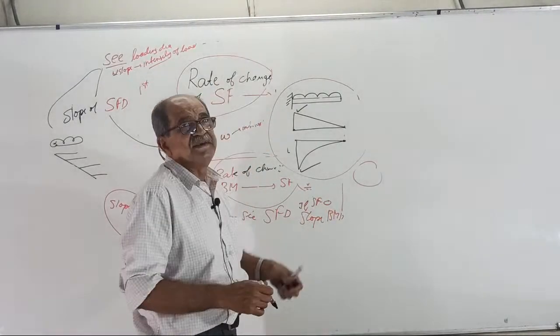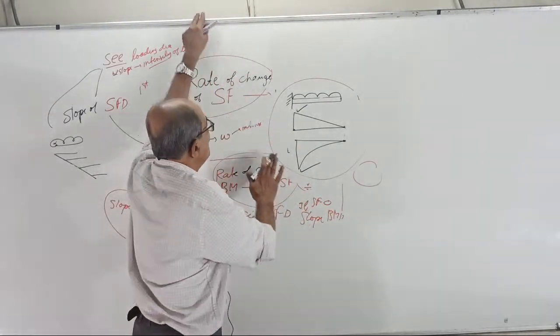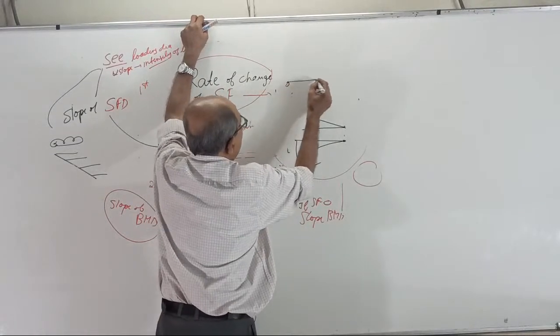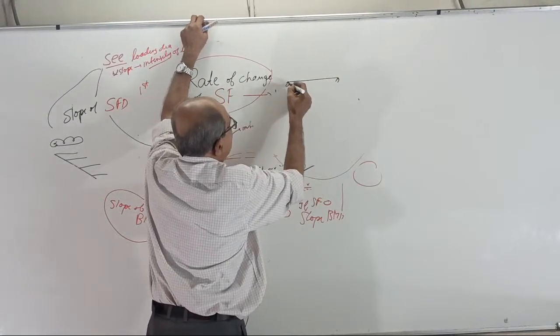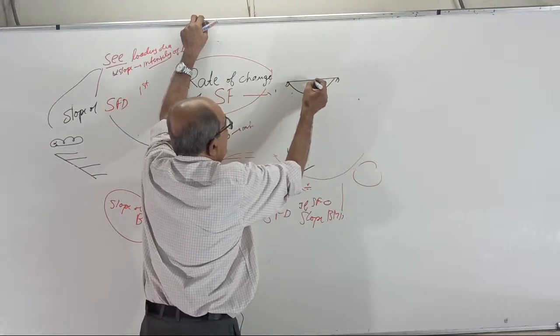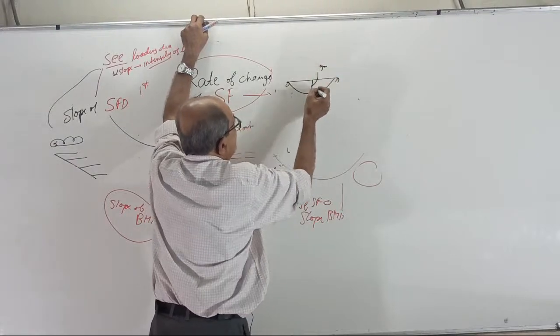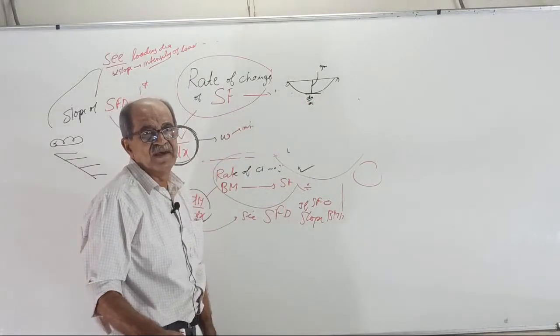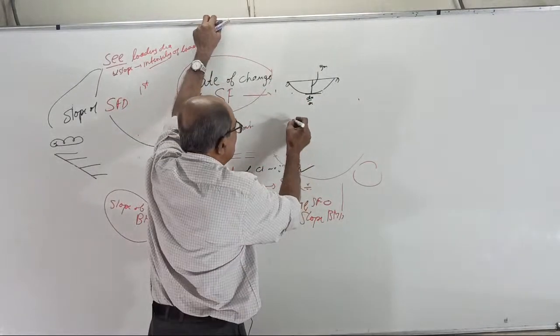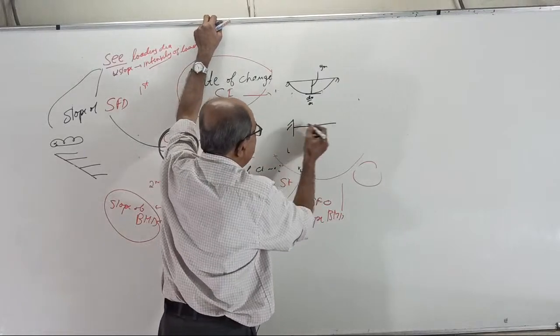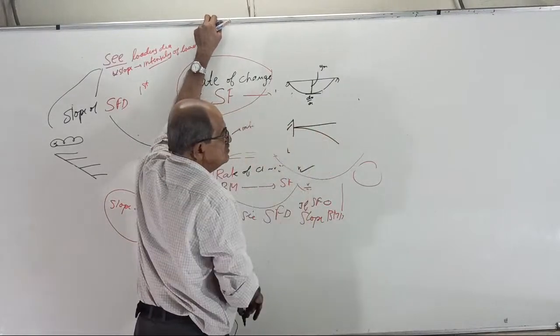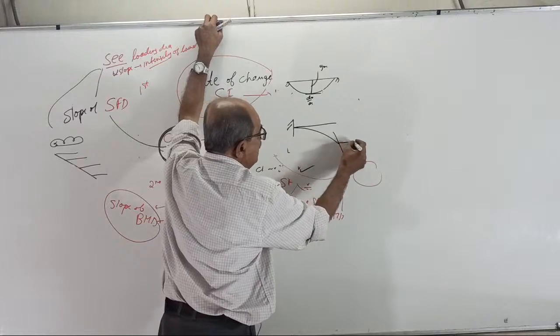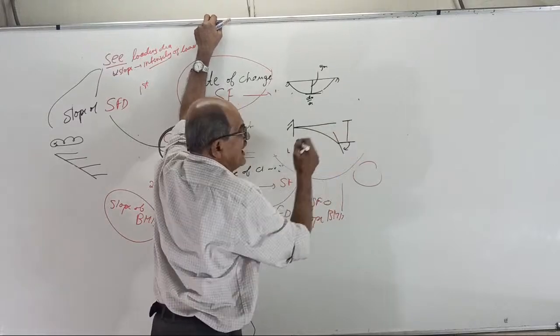See, deflection is maximum where slope is zero. See, again brain teaser. See, this is the elastic curve. Where y is maximum, slope dy by dx equal to 0. I will tell that in the class, deflection class. Then I will ask the question. For a cantilever, this is the elastic curve. Here, slope is maximum, deflection also maximum.